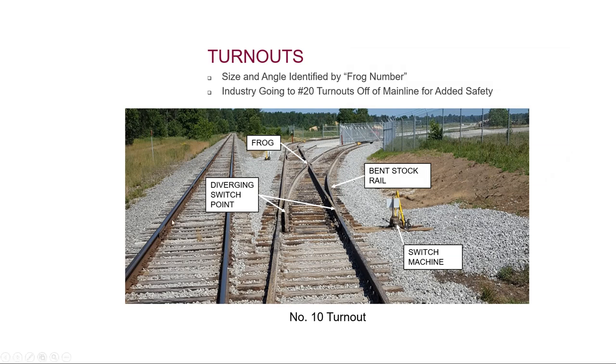All right, well, I said I'd tell you what a turnout is. Here's what a turnout is. If this is our mainline track and we want to have a side track coming off of it, we call that a turnout, right? It's just like an off-ramp for trains. You've got a switch. Back here, the switch slides this rail over against that one, and so the flange of the train catches this rail and follows it this way. It comes across here, it crosses this rail, and it keeps on going for that.